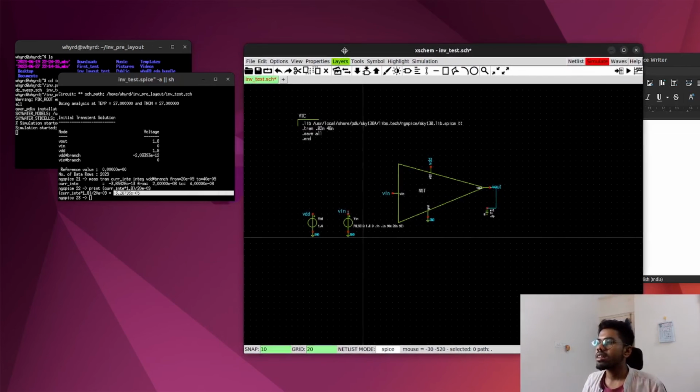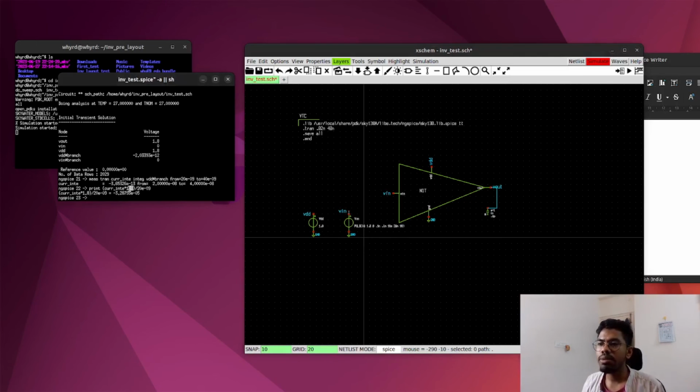Now see, if we can't do it with CL constant, then there is a very easy way, and that is to reduce your VDD. Here VDD is 1.8. If it becomes 1, for example, and see here we are multiplying it, so if it becomes 1, then for sure our power reduces, like from easy maths we can see. So this is another way to reduce the power consumption.